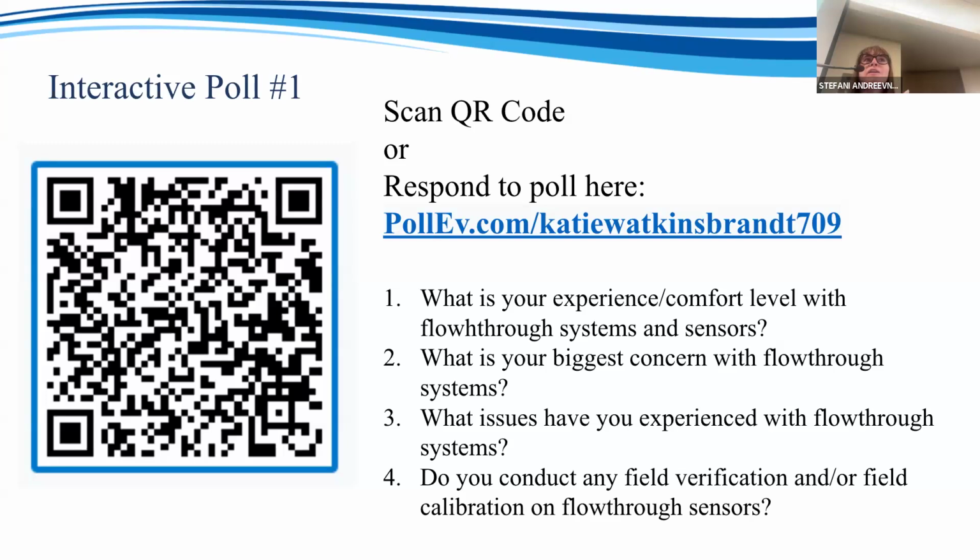It's funny because you guys remember Toby? Toby was like, we have to timestamp right when the sensor takes the measurement, right? I'm like, I think the bigger problem with time is probably how long it takes the water to get from the hull to where it's actually being measured. Because those can be really long residence times, right? And then you think about the thermal contamination that can happen between where your water is coming in and where your actual measurements are being made. That can be huge. And there are some good things that you can do in your flow through system to kind of monitor that.